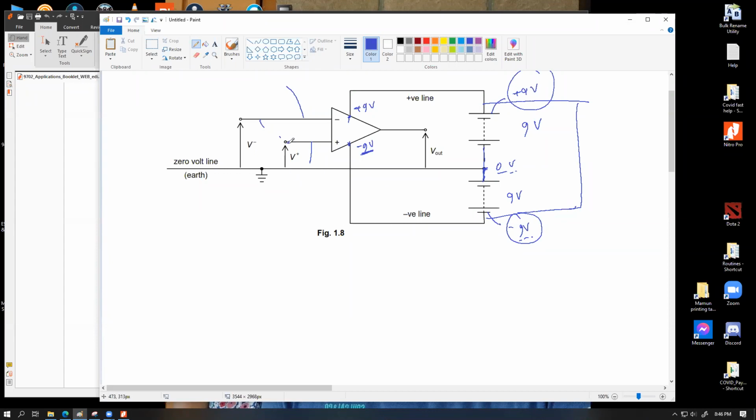How does a comparator circuit work? So this is the circuit for comparator. The name itself pretty much tells what this is going to do. Comparator is going to compare voltages. So to make work of this circuit, we're going to keep one of the inputs, either the inverting input or the non-inverting input, constant, and we're going to change the other one.